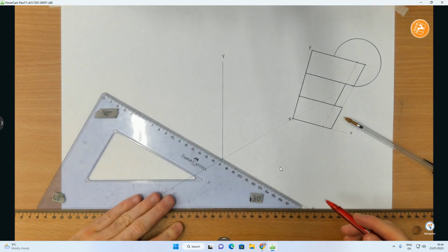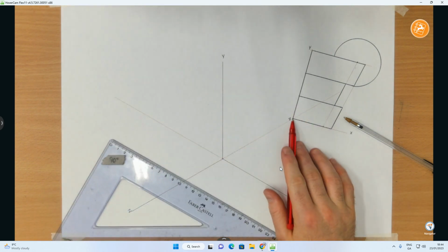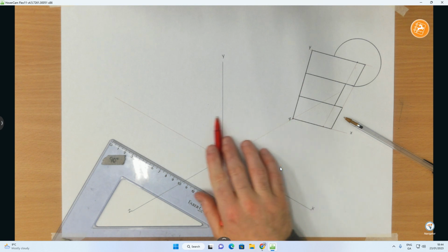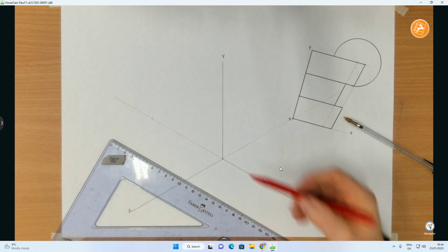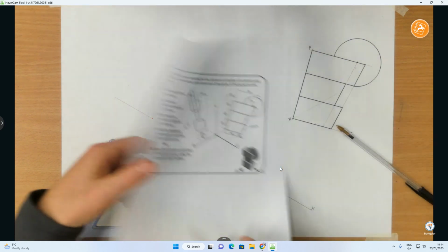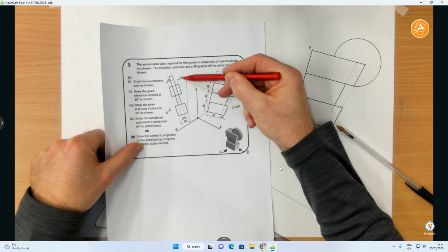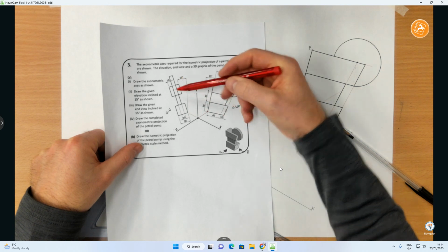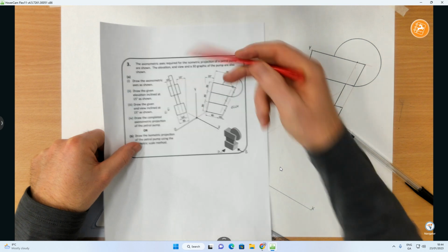So from the x-axis, which is at 30 degrees, I'm going to extend that out. Same principle. What I usually do is pick a distance similar enough to what I did here. So from the Z, I'll just follow with my pen over to here. And now I want a line, and you'll see here a 90-degree angle inside here once again. And you can see once again that 15 degrees. But remember, 90 take 15. That line there is going to be at 75 degrees.